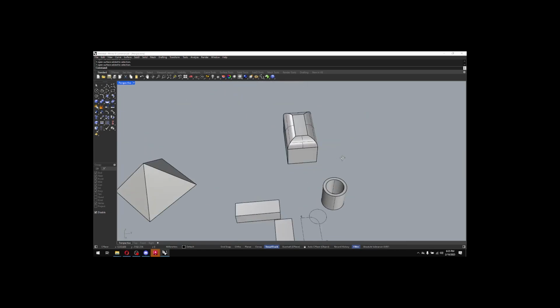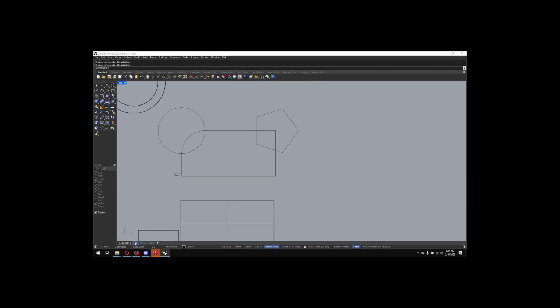Let's talk about trim. That's another AutoCAD one that you all should be familiar with. Line work-wise, works exactly the same. Trim, hit enter. This is how I always explain it. This is how it was initially taught to me, so it always made sense. Select cutting objects. You're selecting your scissors. What's doing the cutting, right? So in this case, we want to trim this piece off. So I'm selecting my cutting piece.